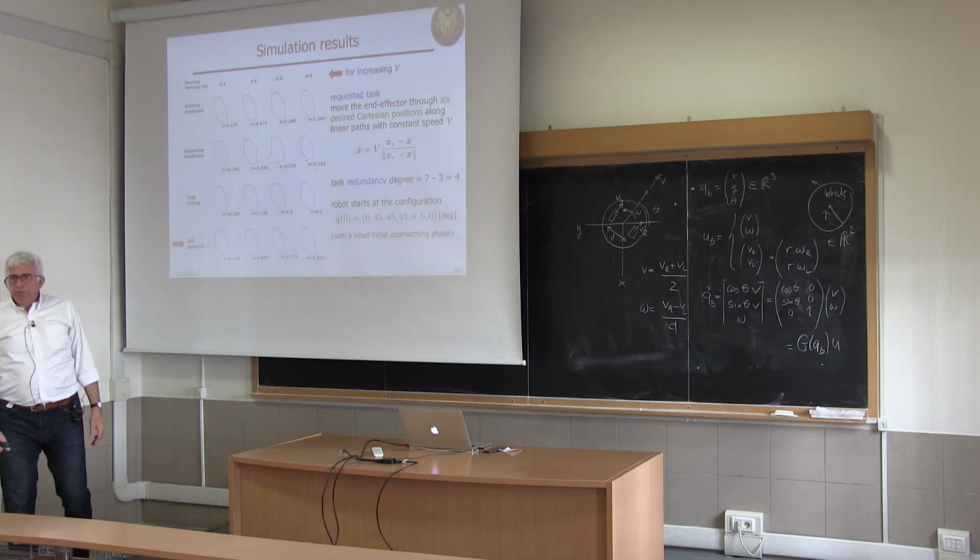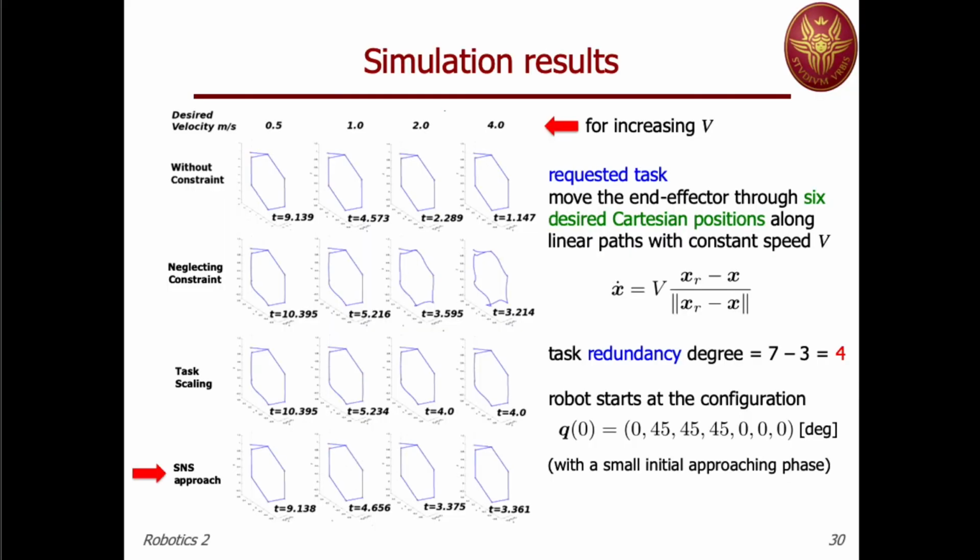Now you're bringing in the constraints, computed as before from all the limits: joint range, joint velocity, joint acceleration. But you're applying your scheme, your pseudo-inverse, in fact, without taking care of the possible saturation. And of course, once you saturate, those joints will be brought into saturation. The joints which are not saturating keep the same value, and you may make some error. In fact, if you're going slow, at 0.5 Cartesian speed, then you take a bit more time.